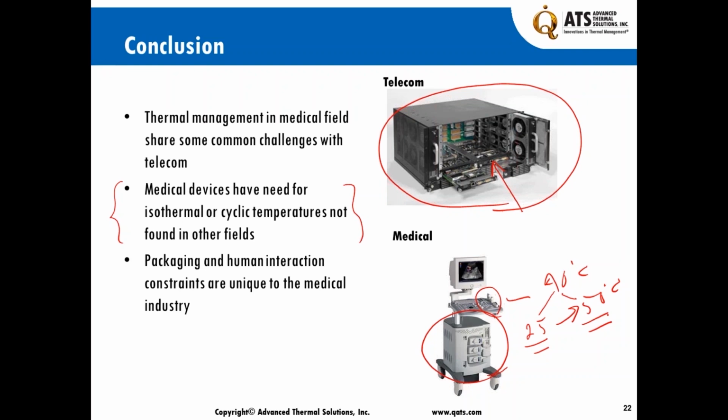When we go through thermal design of any kind of electronic system, we always start from the ambient and go all the way down to the device. So we start from the ambient, where the system is going to reside, the deployment site, and we go to the chassis. We go to the board, and then we come to the component here for junction temperature level management. This is where the junction temperature is managed, the T sub J.